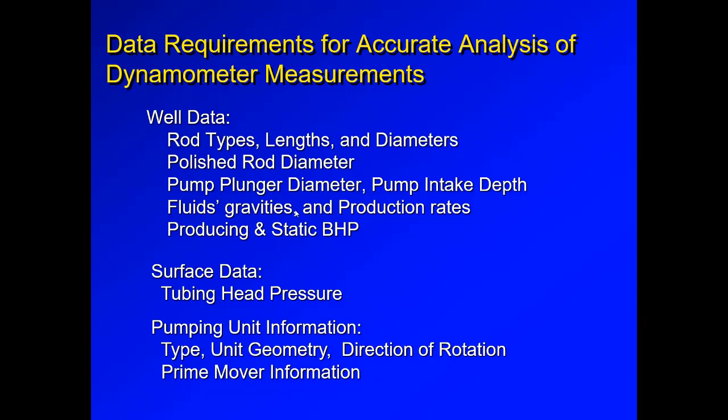And you can enter the fluid gravity, so be it API, water specific gravity, and so on. Production rates, so you can compare the production rate to what the pump is calculating. Look at making better fine tunes on your adjusted pump displacement calculation. We will discuss a little bit more about that in the next slides, when we're looking at some dyno cards, about how the software calculates pump performance, pump displacement.